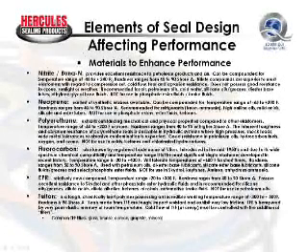The nitrile or Buna-N provides excellent resistance to petroleum-based fluids and to air, and it can be compounded for a temperature range of -40 up to 240 degrees Fahrenheit. Its hardness can range from 40 to 90 Shore A. We will talk about the measurement of hardness in just a few minutes.